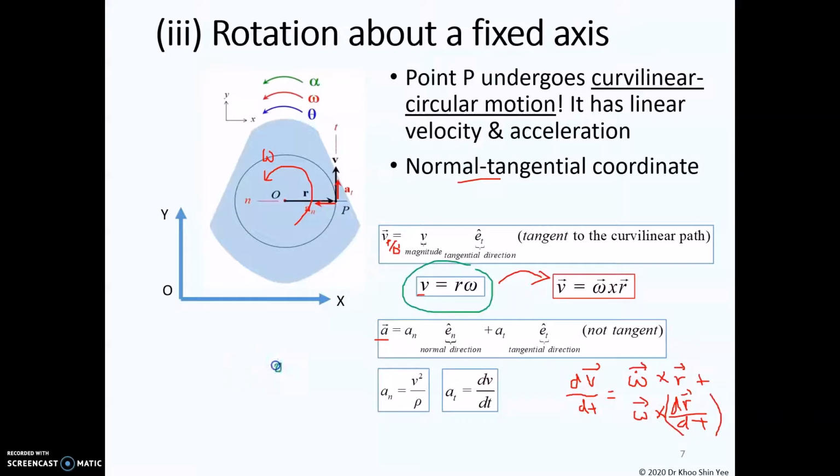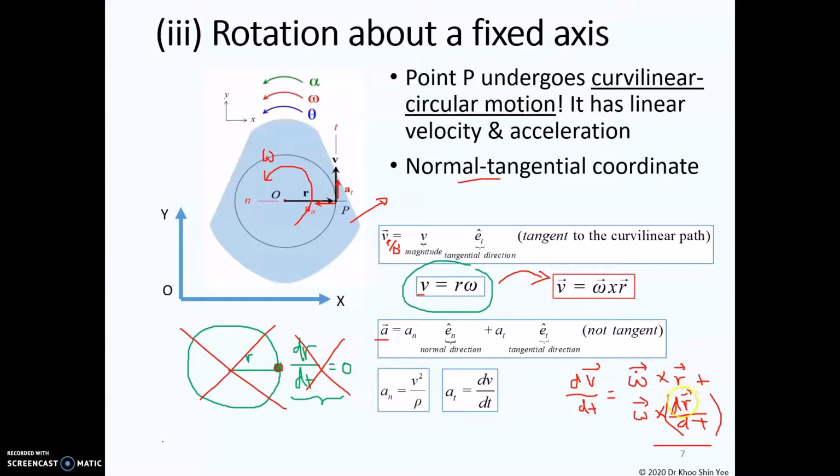You need to be careful for a particle that is doing the circular motion. In this case, the radius will be equal to constant. If you want to know what is the dr over dt in this case, since the r is constant, therefore you obtain 0. This is scalar analysis because we are using the scalar quantity r for the calculation. However, in this study, we can no longer treat the rigid body as the particle here. We are performing the vector analysis for the rigid body instead of the scalar analysis. So don't mix the usage here. You must understand what is the r vector here.